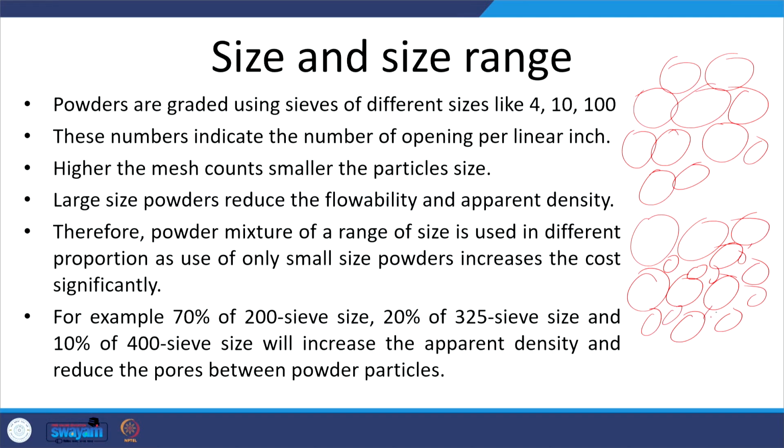If we use powders of different sizes, then the voids and porosity without compaction will be less. Therefore, to reduce the interparticle porosity, to reduce the voids between the powder particles without compaction, it is important that powders of different sizes are used.